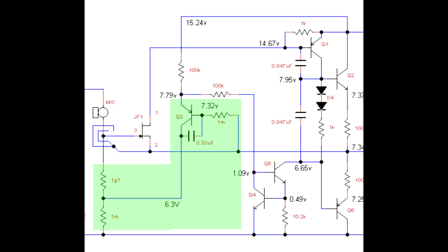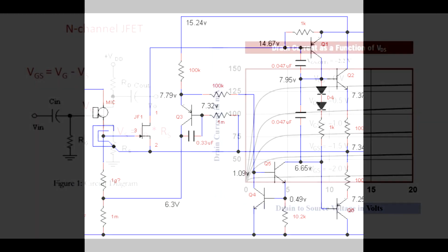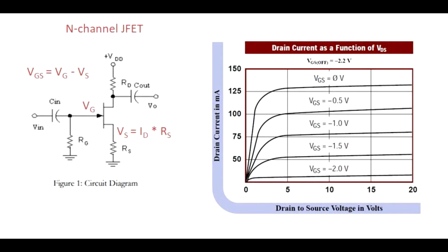The JFET transistor will have an internal capacitance from gate to drain and gate to source, and so you need to control that because we're talking about very, very high impedances and very, very low capacitances. We need to somehow negate those things, and we do it in this circuit with a bootstrap. This schematic shows a typical JFET amplifier with self-biasing. You can see that the gate resistor is placing the gate at 0 volts.